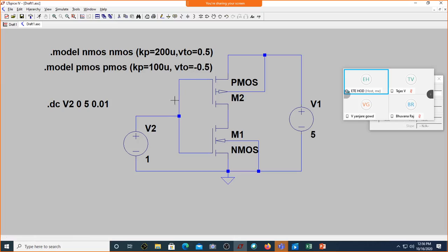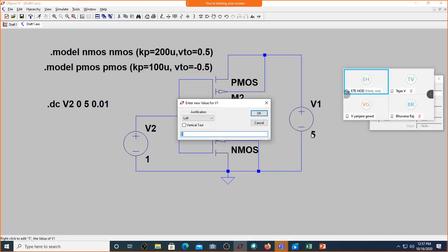If you want a very good noise margin, this should have a transition point happening exactly at the midpoint of VDD. That is possible if the dimension of the PMOS transistor is mu n by mu p times the dimension of the NMOS transistor. What is the mu n by mu p ratio here? 2, sir. So that's why I made it exactly equal to 2. The transition of your output from VDD to 0 was happening exactly at the halfway point of VDD.